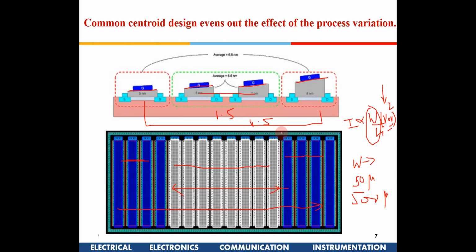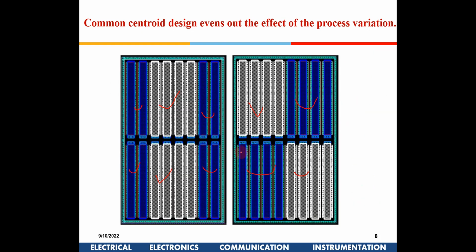No, generally when you do a process on a chip towards the edge, there will be some process variation in some particular direction only, right? It will not be random variations. Generally during fabrication that can happen. Not at the center of the chip, only towards the corners you will find there is some variation happening. But however, in the next slide, you are arranging it alternatively, right?